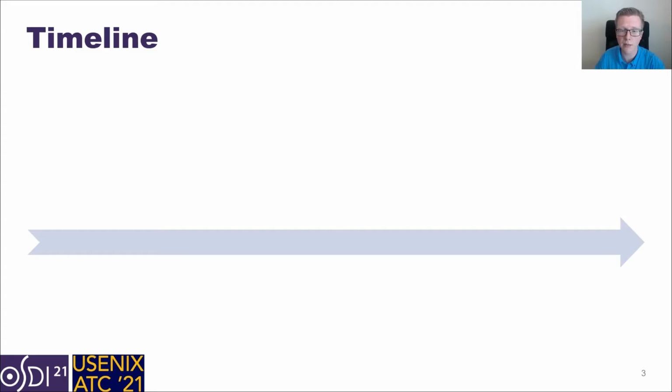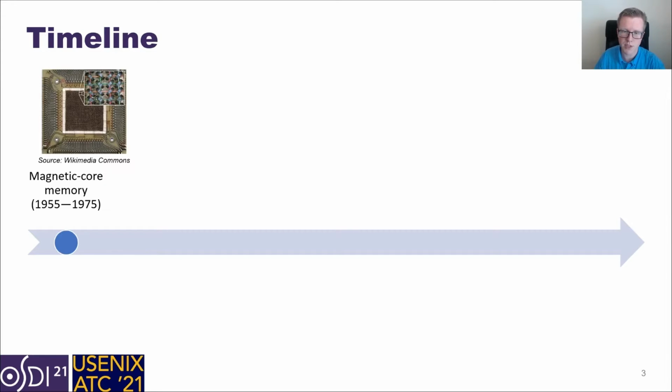To understand why modern persistent memory research is so focused on non-volatile memory, it would help if we could understand a bit of the history of persistent memory technologies. The first persistent memory technology, magnetic core memory, was actually the predominant form of random access memory in computer systems in general. This kind of memory worked by using electric current to magnetize little ferrous toroids, and the cores would stay magnetized until acted on by some other electrical force. Coincidentally, these core memories are the origin of the core dump terminology, which you may have encountered before.